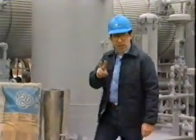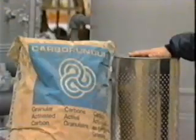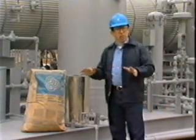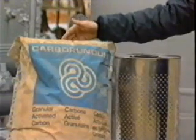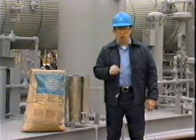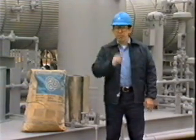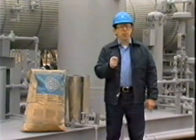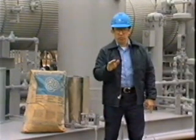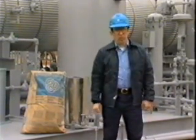Now, there are two types of activated carbon filters. Small systems like this one use a carbon canister with replaceable cartridges. Larger systems use a loose-fill carbon vessel that uses granular activated carbon. When the loose-fill vessel is used, carbon particles, sometimes called fines, must be trapped to keep them from entering the glycol dehydration unit. This is especially important when a fresh carbon bed is put into service. Anytime the level of contaminants in the glycol increases, the carbon filter should be replaced. Monthly tests should be run to determine contamination level.